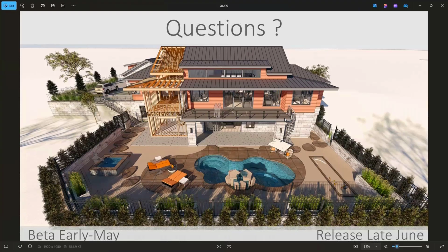Okay. So when you go through the import wizard in the program and you point it to the DWG file that has the survey information in there, you can then flag the terrain perimeter and the elevation data.